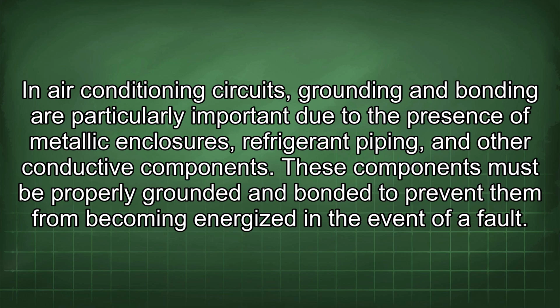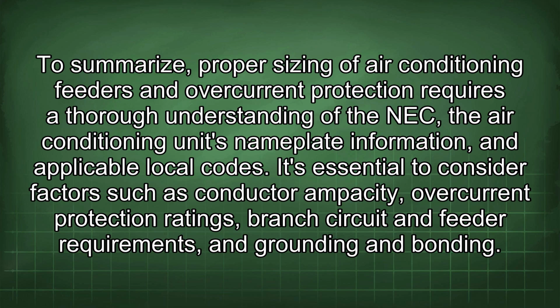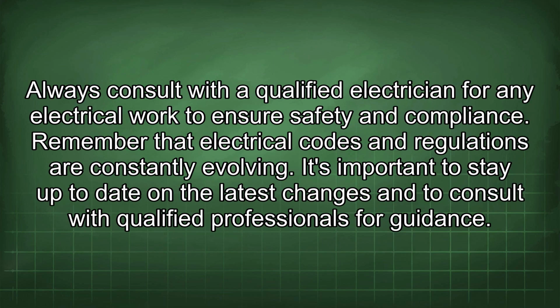of a fault. To summarize, proper sizing of air conditioning feeders and overcurrent protection requires a thorough understanding of the NEC, the air conditioning unit's nameplate information, and applicable local codes. It's essential to consider factors such as conductor ampacity, overcurrent protection ratings, branch circuit and feeder requirements, and grounding and bonding. Always consult with a qualified electrician for any electrical work to ensure safety and compliance.